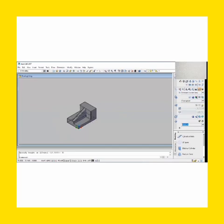But you can see that it has some lines here to separate this. It looks as if there are different parts that have been joined together. So we need to use the union command. You can see this is the union command. You left click on the union command and then highlight everything. By the time you highlight everything, it means you are turning this into a single block, not a block with several parts. After you left click, you right click outside. So you can see this has turned into a single block.